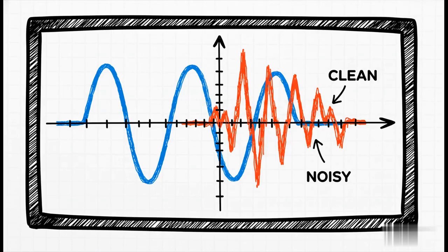And wow, this slide really drives the point home that even with the perfect circuit, your choice of instrument matters a lot. What we're looking at here are two different current sources. That blue line, nice and clean. The red one, yikes. It's incredibly noisy, throwing out all these energy spikes that can totally corrupt your results. It could even make it look like a device is switching on when it really isn't. It just goes to show you, not all equipment is created equal.